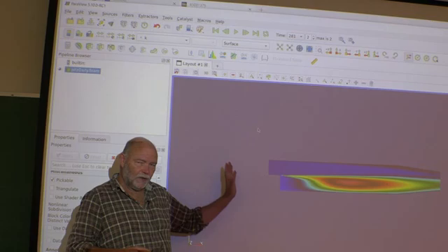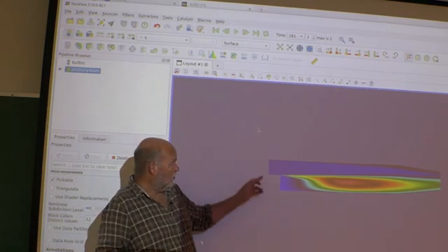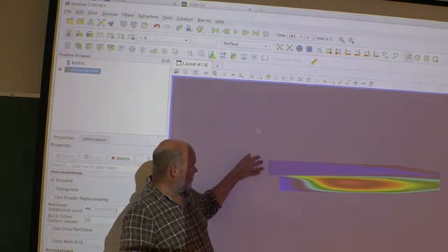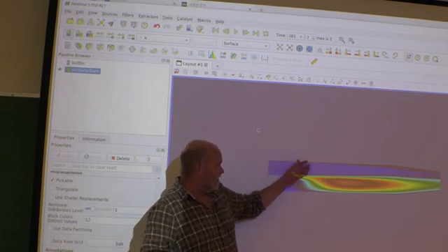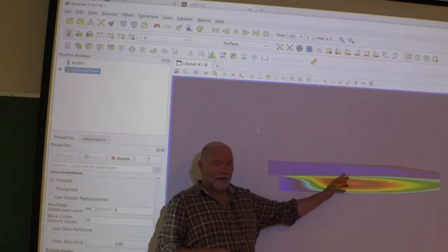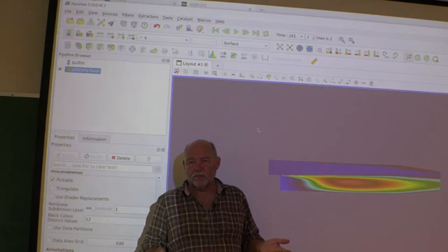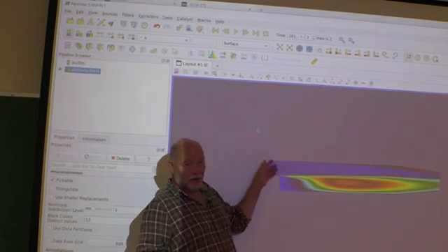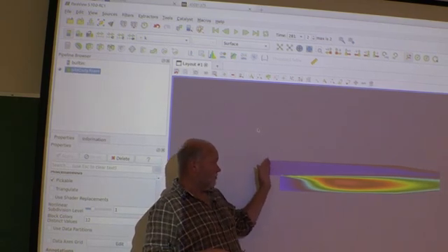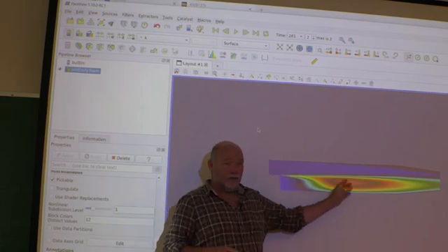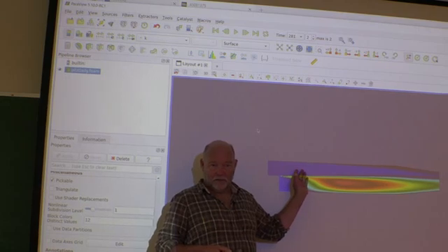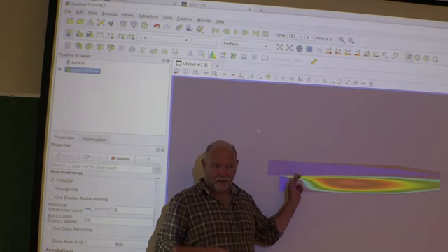And then when you do a simulation, you check if you have put in a way too big number here, then you will see something coming in here, and then you won't see anything else. And what you send in is going to die out quite rapidly. Then you have a way too big number. The value at the inlet is way too high. The other way, if you send in too small a value, then you'll hardly see anything. I mean, the turbulence is sort of killed before you even begin. So you have a look at these plots.